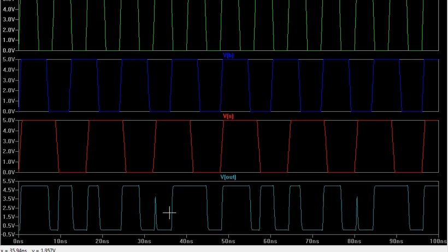Now let us try to understand the output with respect to the input. As we have discussed in the truth table, whenever S has a value of 0, my output will be connected to A. So A has a value of 0, so that 0 will be coming here at the output. Whenever S goes to 1, whatever value is present in B will be coming. So in B, I have this particular signal, and the same signal will be replicated at the output. And you can cross verify at any point of time.